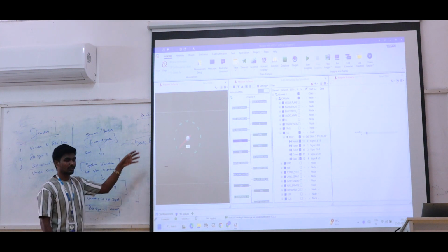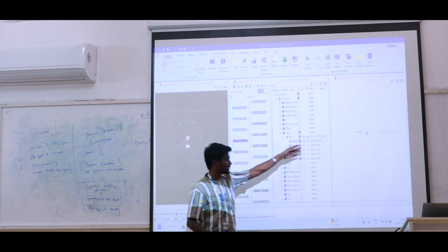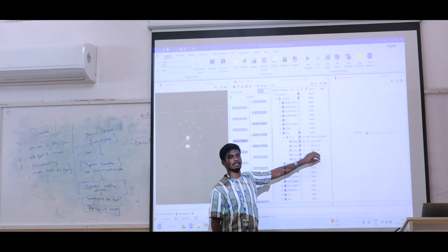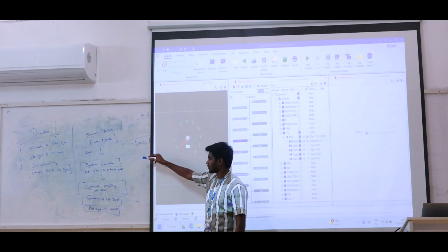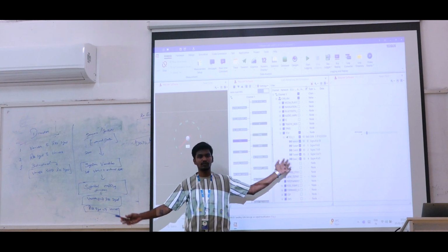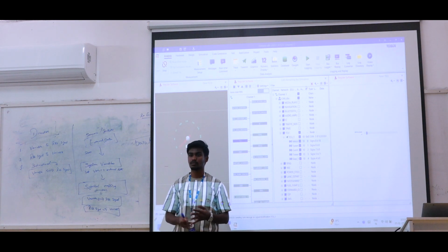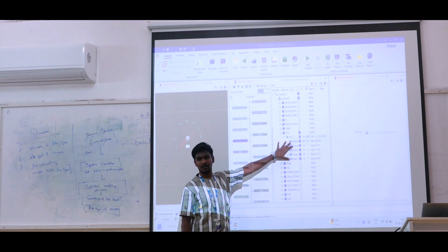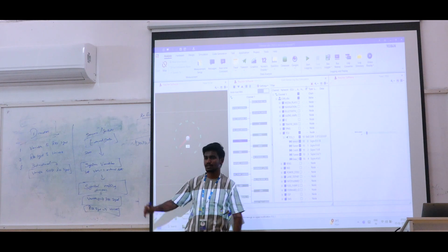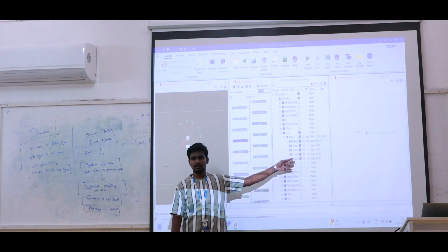Or else, we will take a temporary variable and work with that signal, where we can generate some signal values here, but we are not affecting the signal. We just take the values and store them in one more variable, like variable 2 or variable 3, we can create it. The signal value we can store here and do some scripting operations. At that time the signal will not be affected, whatever coding we do. We will just check with the system variable. Once our feature is tested, we can apply the same to our signal.